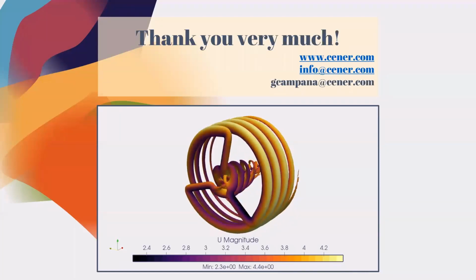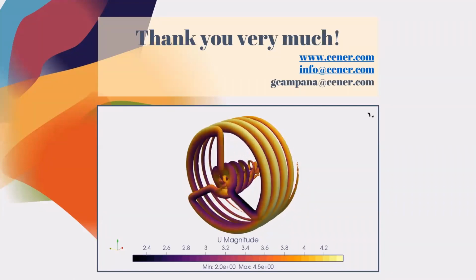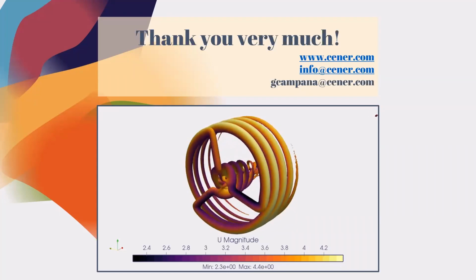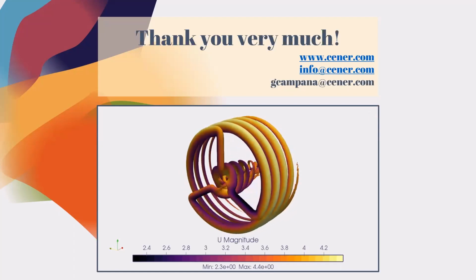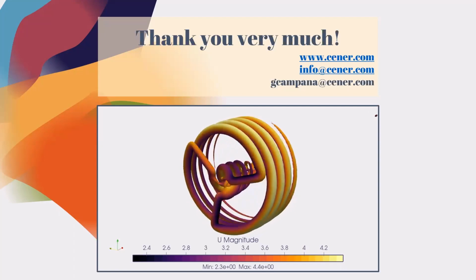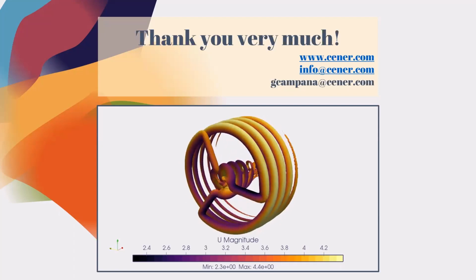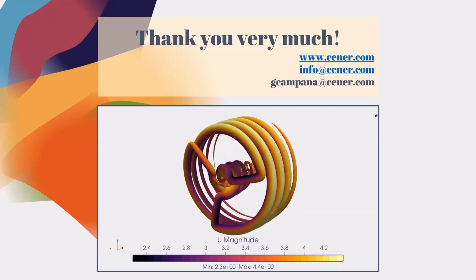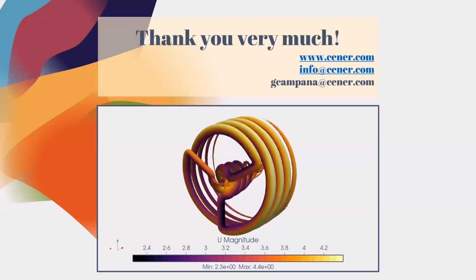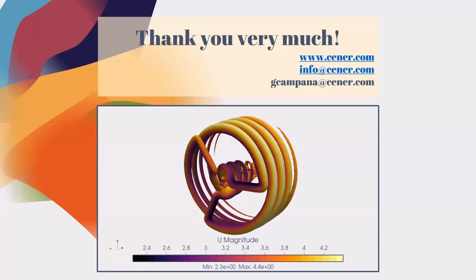It was simple Smagorinsky for LES, and for RANS it was k-omega SST. It is not needed because there are no walls, but just to make a fair comparison when we use a fully resolved approach, that is also k-omega SST. Yes, we have computed also in a finer mesh that resolves properly the scales, but I wanted to show the differences between a RANS simulation and an LES simulation with the same mesh. Snappy, blockMesh and then refinement zones with snappy, yes.